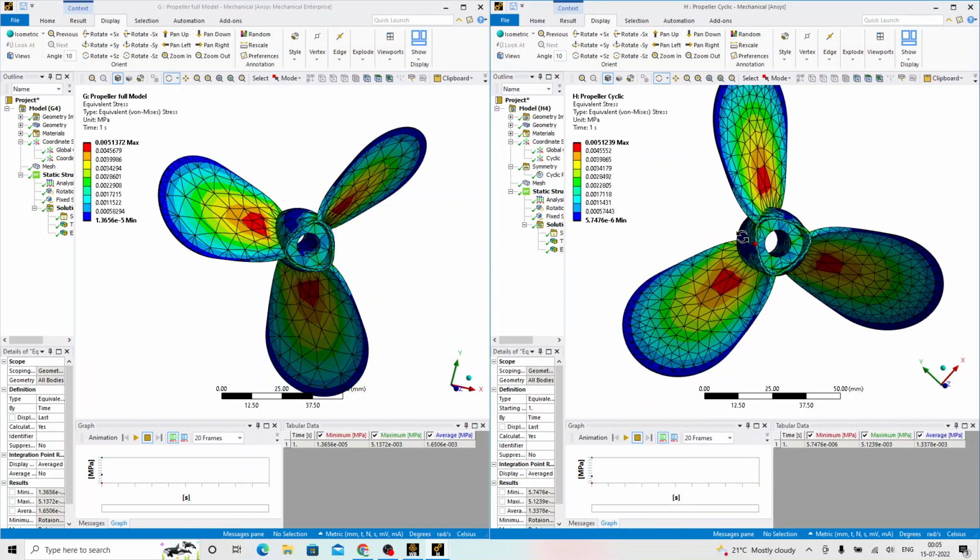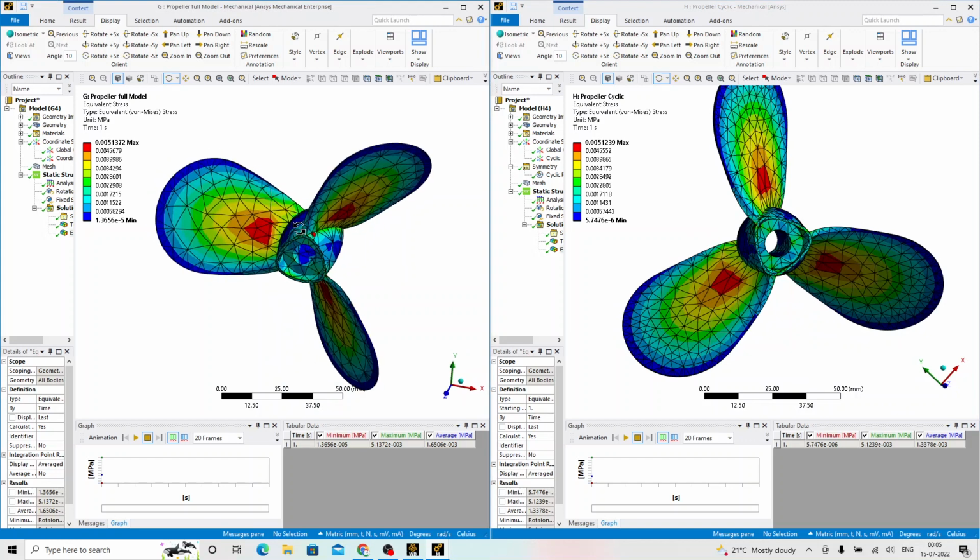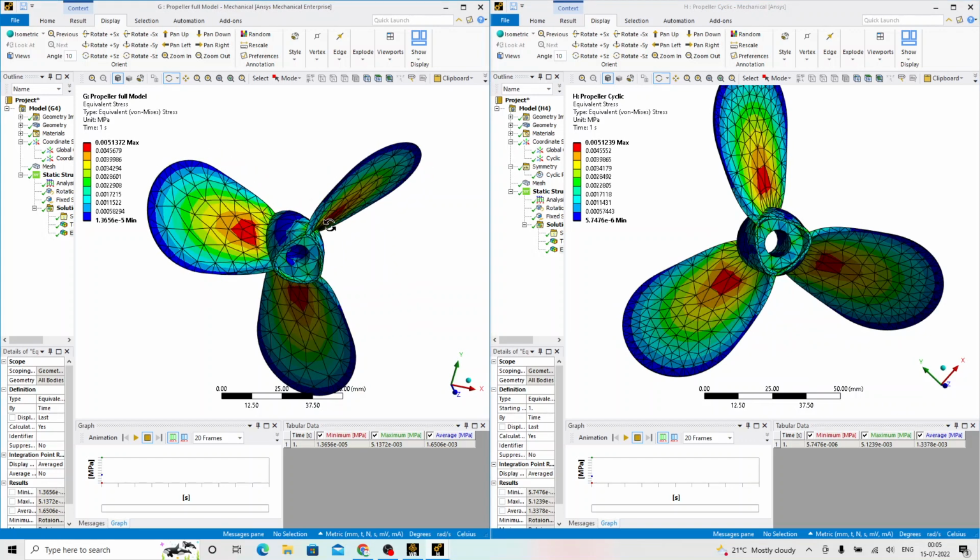This is how it's going to look like. And look at the pattern of the stress and the deformation. They are the same. What is the benefit we got here in doing all this analysis? The benefit is computation time. In finite element analysis, computation time is very, very important. Having the control about this computation time, trying to solve the problems faster, will help you to conduct more iterations in a given amount of time.